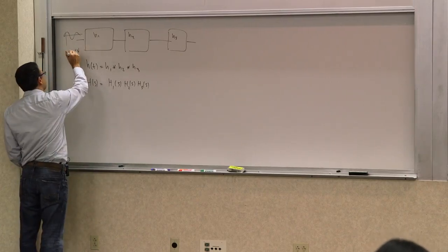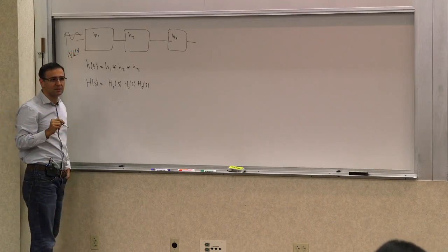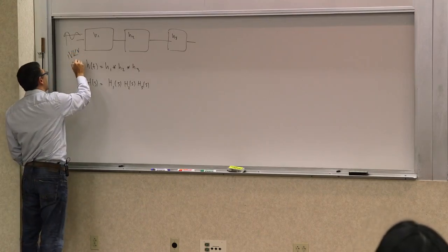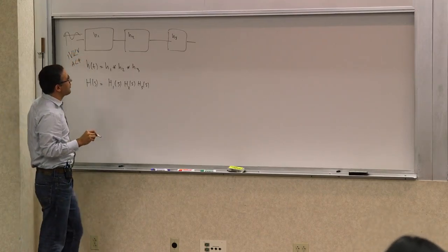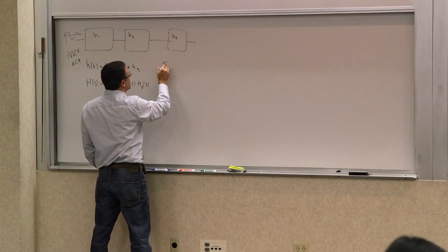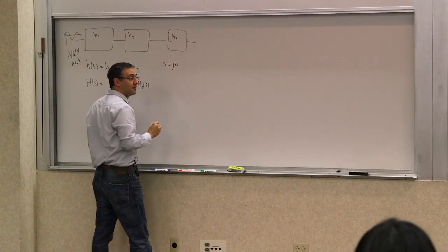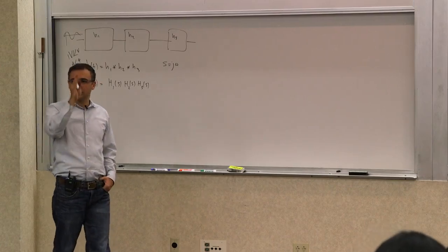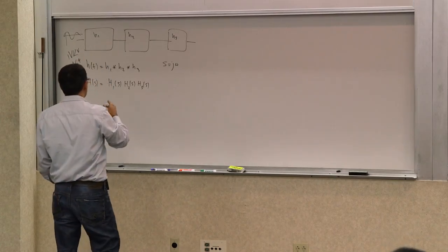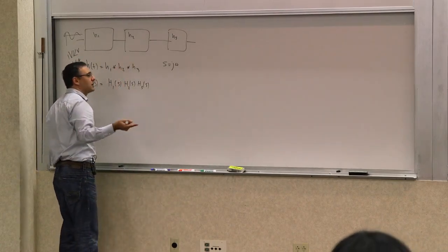Right? So you have the magnitude and the phase of the system. You could have basically the amplitude and the phase, if you will. And we used those to determine this. So in other words, we looked at s being equal to j omega. We looked at it under a special case when you're looking at the j omega axis. And we perturbed the system. And that led us to the Bode plots.